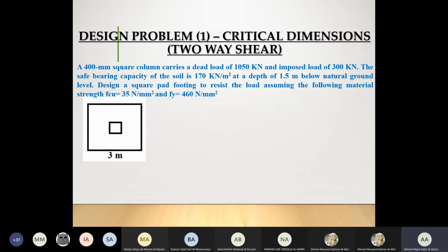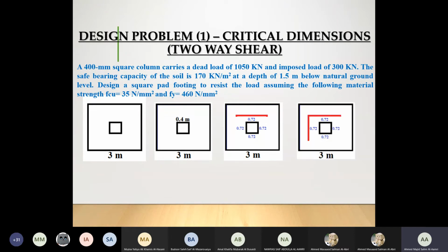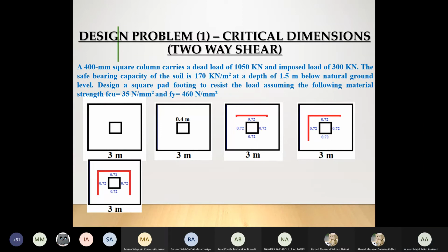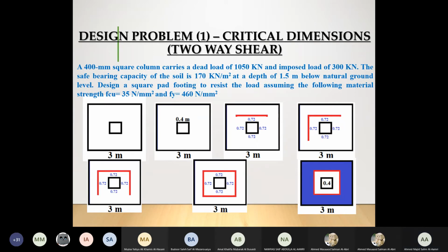The same thing goes for two-way. So we have 1.5D. So 1.5D is 0.72. Okay, so we have calculated all the sides and we have come up with inner and outer area. And now we need to calculate this particular blue color. This particular blue color is the portion which will go up. And we need to know how much force is required to take this particular portion up.